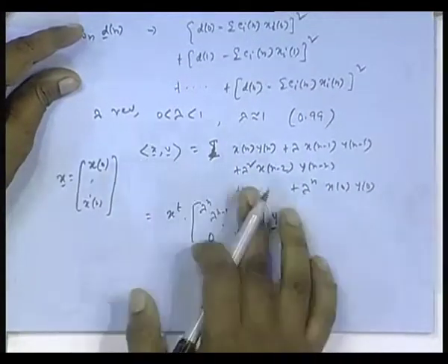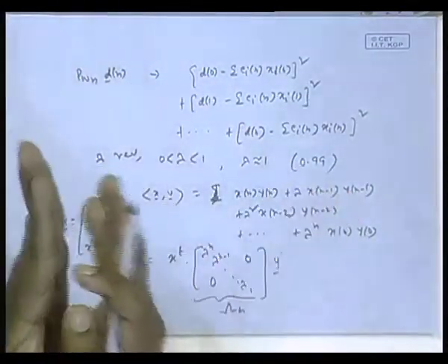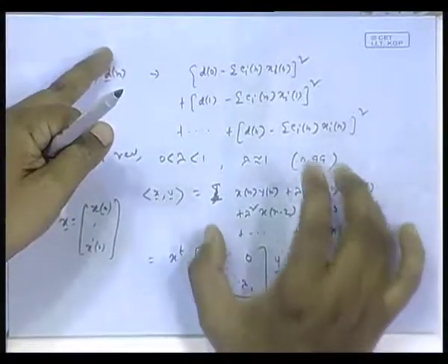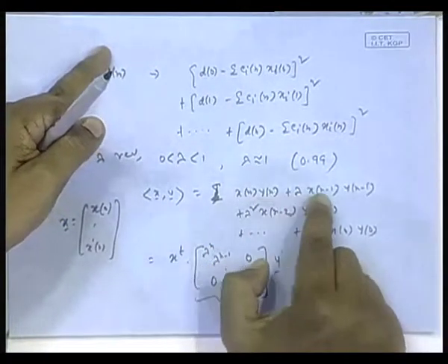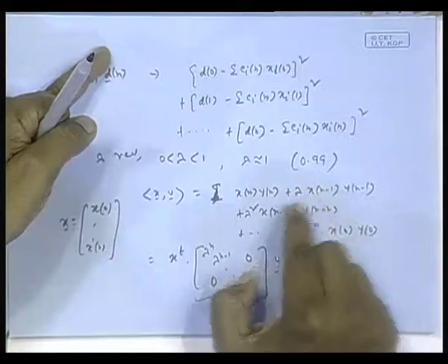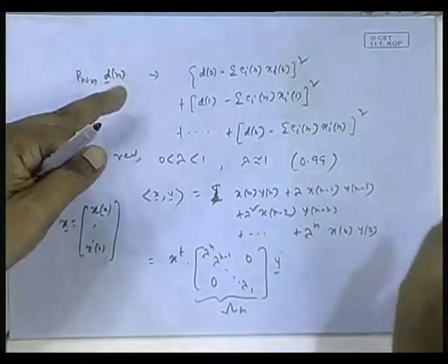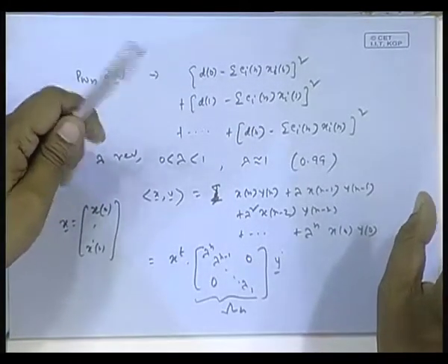If you use this in an inner product, and make it a variance, and that too the variance of the error, because after all, while computing the projection, you will be finding the error vector and minimizing variance. In that variance, if you want to forget the contribution from the remote past, n equal to 0, n equal to 1, and concentrate mostly on the current ones, then these weighting terms will take care of that. In the sum of square, the dominating part will come more from current ones, x n y n, or maybe lambda times x n minus 1 y n minus 1. If it is variance, x n square, then lambda into x n minus 1 square, lambda square into x n minus 2 square, maybe a few more terms; other terms will be sufficiently suppressed. So, lambda will be part of the algorithm.